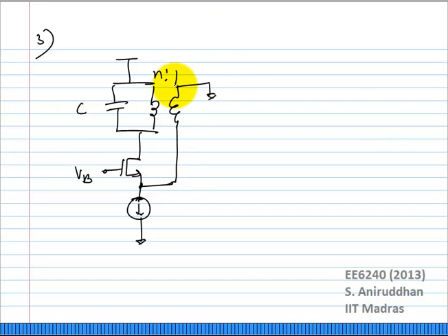Alright, you need to go down, remember. You need to feed a fraction of the signal back. Instead of using a tap structure, you can use a transformer. There is a very fundamental reason why you need to use this kind of downward transformer. Of course, fundamentally the amplifier amplifies the signal, so you only need to feed back a portion of the signal.